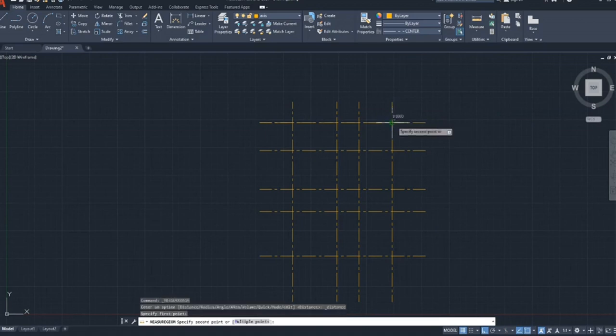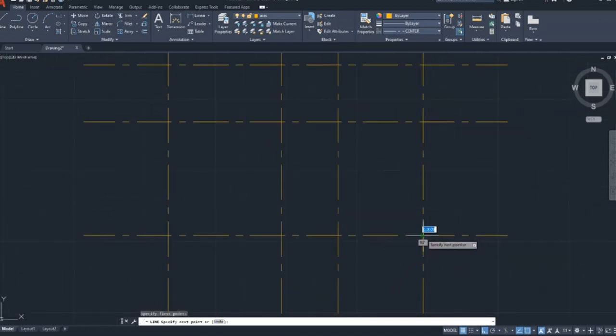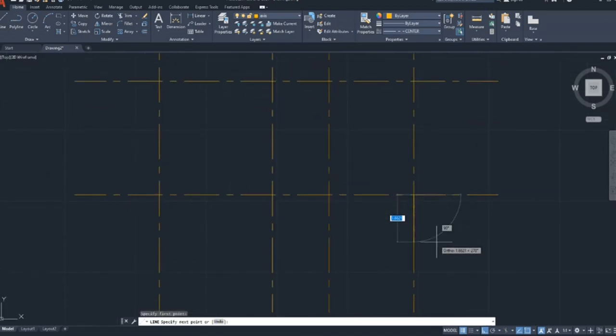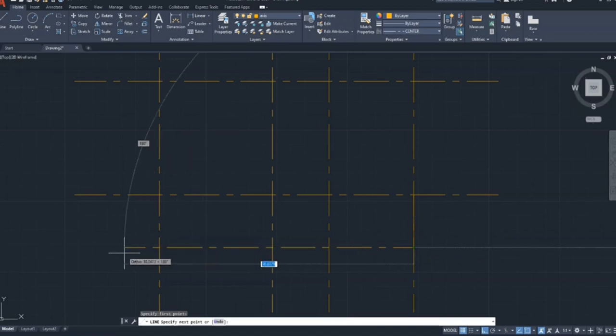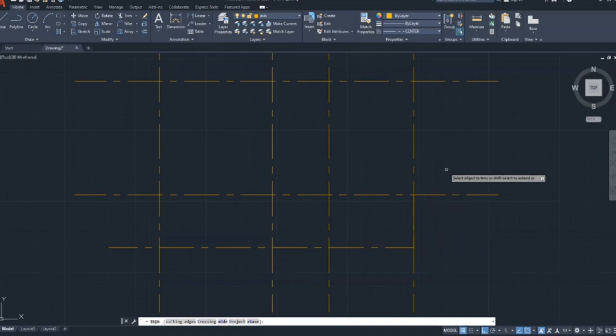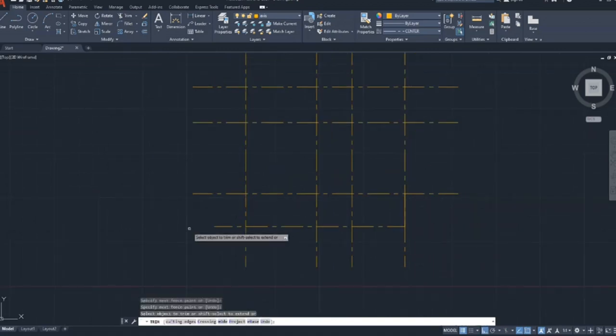At this level, it might feel convenient, but in the long run, it could prove to be a hectic routine. All this work could have been done by using an appropriately dimensioned and to-scale line segment, and then using the offset command one time for the vertical lines and one time for the horizontal lines could have done the same.